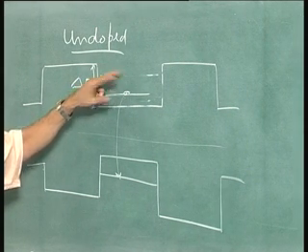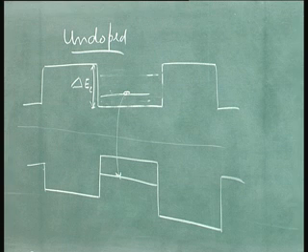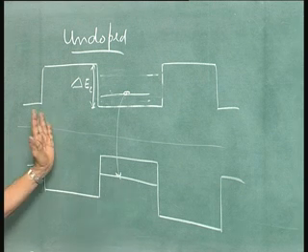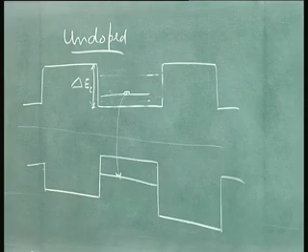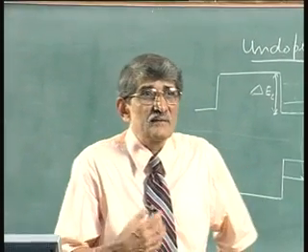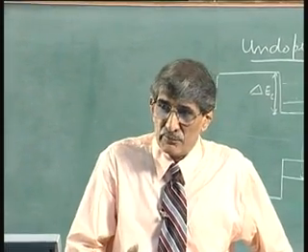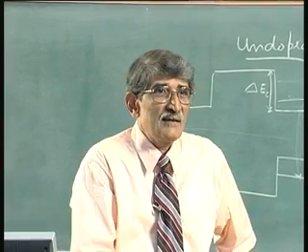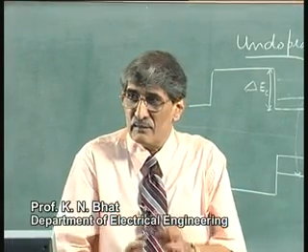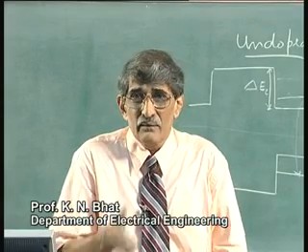So, you can see the compound semiconductors give you the facility not merely to adjust your band gap by changing the material composition, gallium arsenide, GaAs to AlGaAs. By changing x you can change the band gap, plus multiple layers you put alternately, it gives another dimension altogether. So, for optoelectronics applications, that is another thing.